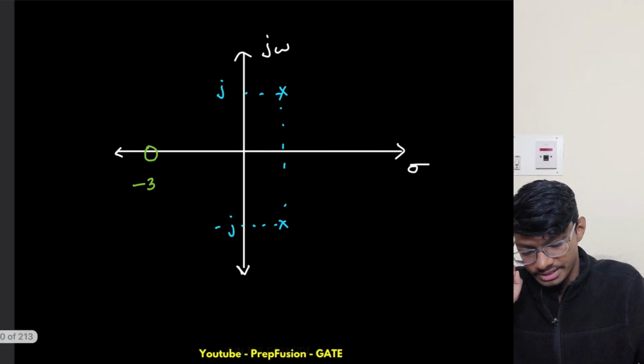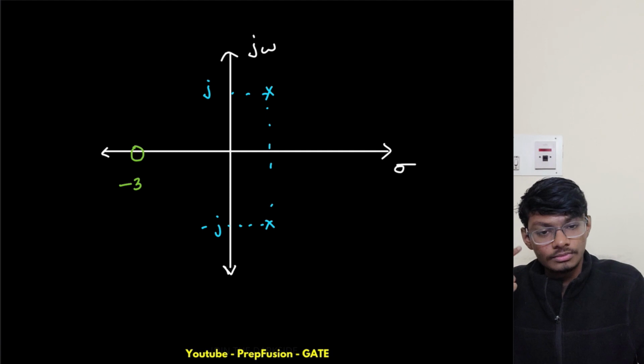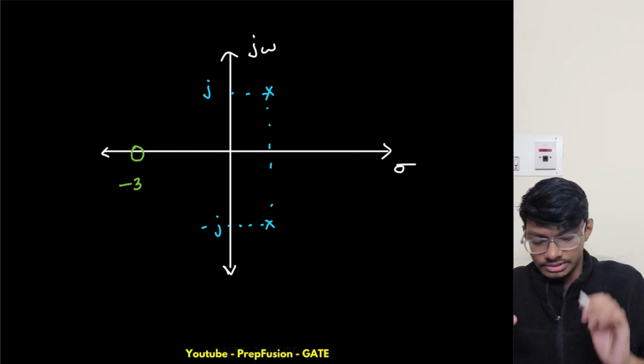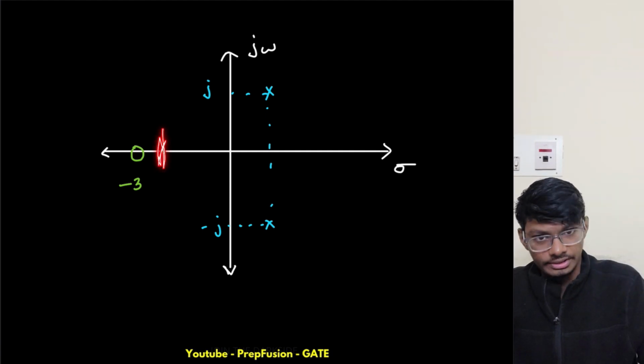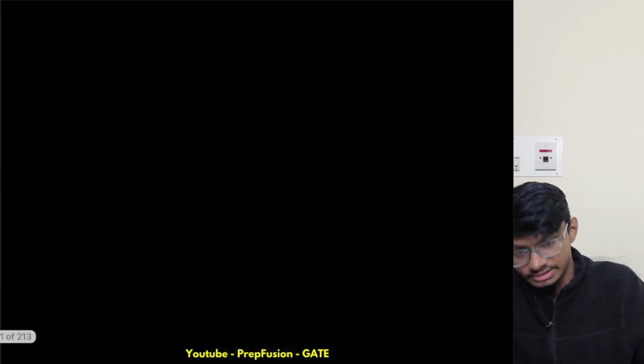So basically, from intuition, what you can say is that obviously my test point won't lie around here, right? That is step 2. So let's do step 2 itself. Step 2 is basically finding the valid location of my closed loop poles on the real axis.